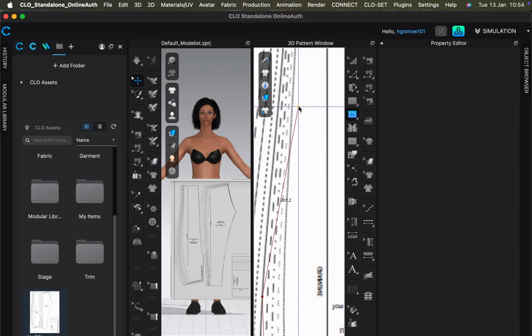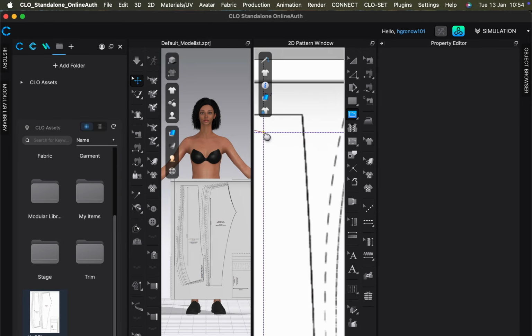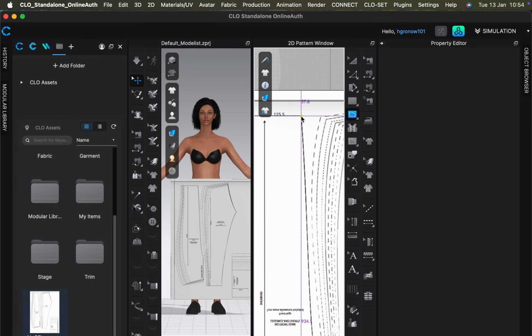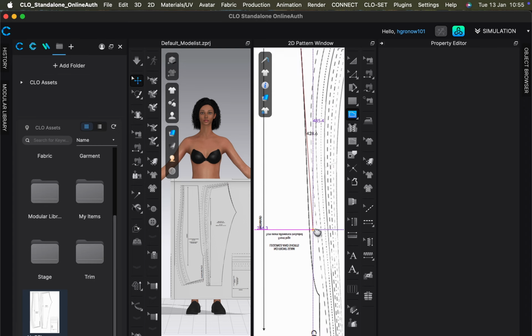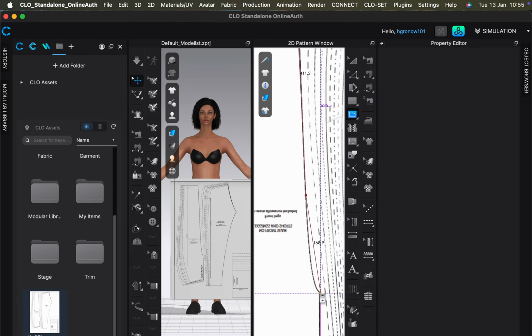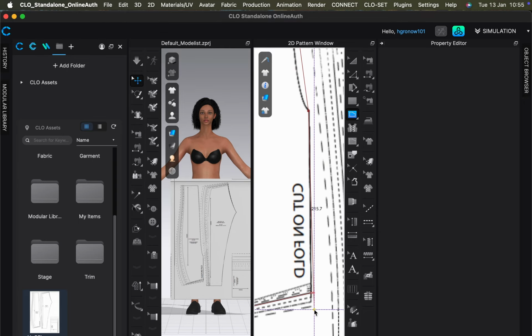You can see as I trace round, a small scrunched up hand sometimes appears on the window. This comes up when I'm dragging my canvas around to try and reposition. This is the pan setting. You can use the pan to navigate round both the 2D and the 3D window. I have my settings set to left click and Alt or Option on Mac. You just need to find out what suits you and set it in your user settings, which I showed you earlier.